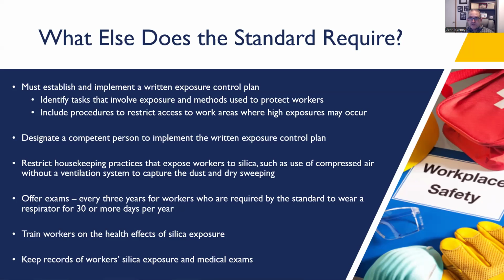Let's take a look at a commercial roofing project or a low slope roofing project where we're going to be cutting into a reglet, or we may be drilling into concrete or mortar, and we get the exposure of the dust onto the decking or onto the roofing, and we need to clean it up. You will create a high exposure if you do sweep or blow this with a blower. So those are the things you must keep in mind of what you need to do to protect and put into your plan.